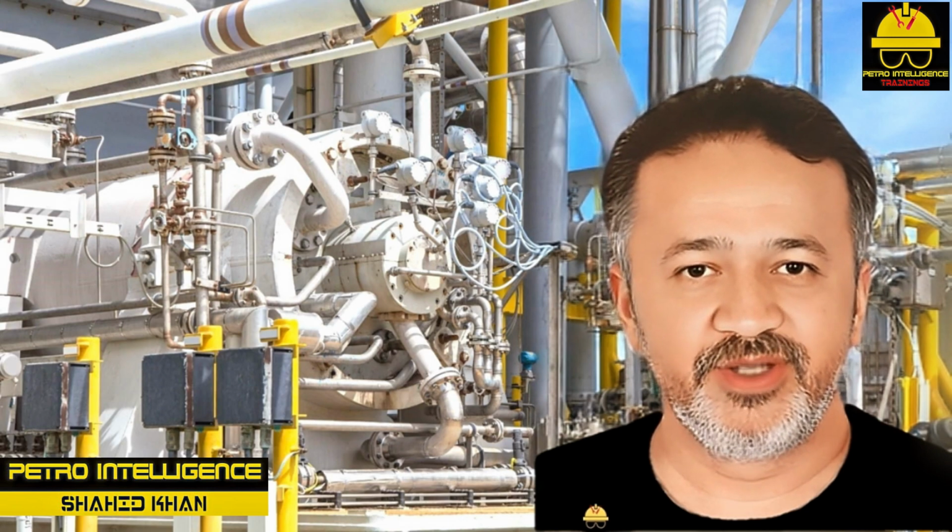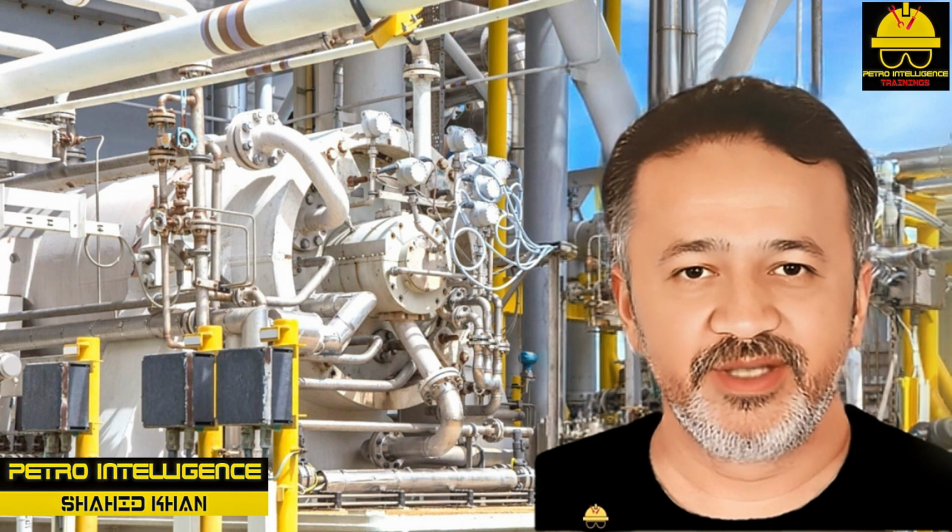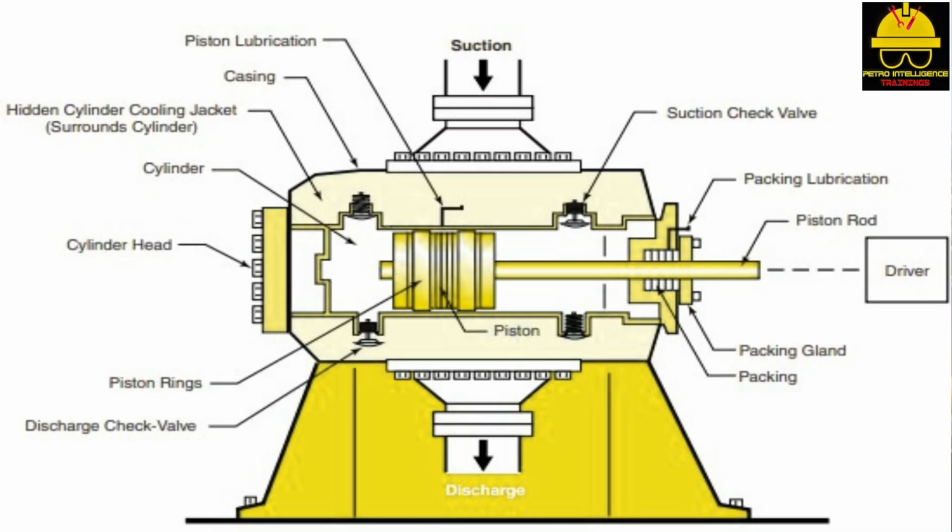Reciprocating piston compressors. Their distinctive back-and-forth motion characterizes reciprocating compressors. Reciprocating compressors are classified as either piston or diaphragm. Diaphragm compressors utilize a hydraulically pulsed diaphragm that moves or flexes to positively displace gases. We discuss only the piston type because it is the most popular design. Equipment ratings from fractional horsepower to over 20,000 horsepower are possible on reciprocating compressors.